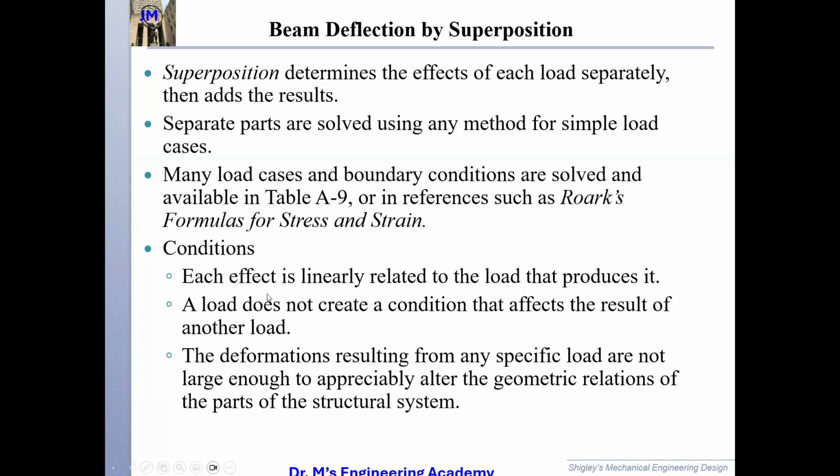So these are the assumptions. To be simple, for superposition you should have small deformation and also elasticity, so we can guarantee that from the perspective of material it is linear, and from the perspective of geometry it is also linear. Questions regarding this slide?